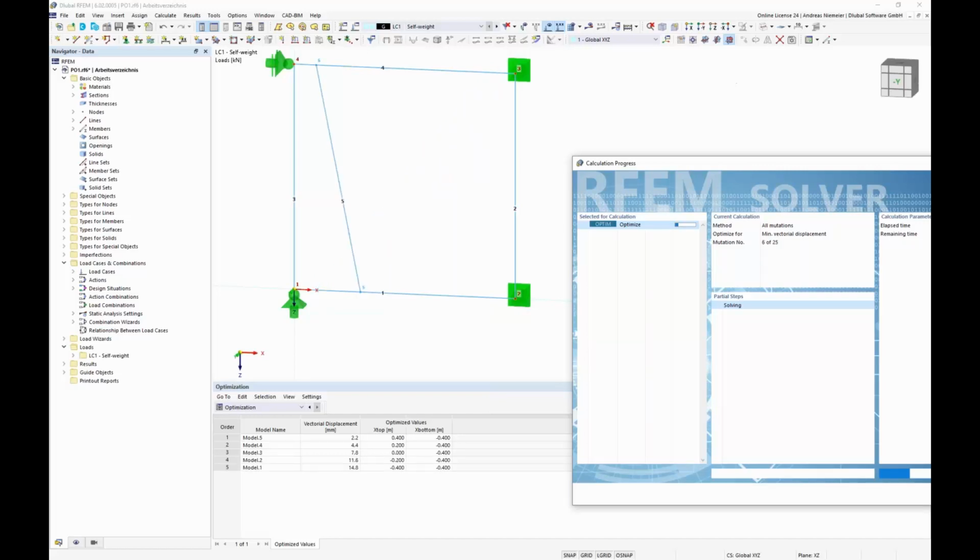Now we log down the 25 best results, and you see you have here measured the vectorial displacement and the corresponding parameter set. The best vectorial displacement, for example, happened now with solution number 5, if it moves the top node 0.4 meters right and the bottom minus 0.4 meters left. So this is, let's say, our expected place, which is really good. All others are not so good, so you see we get bigger deflections here. But of course it's a stupid process because it calculates all available.